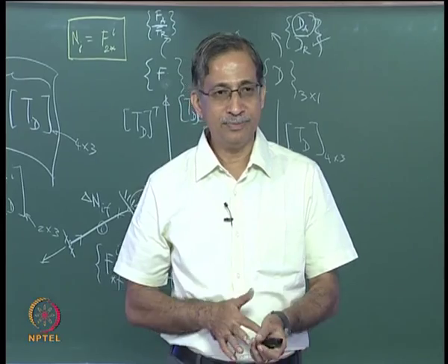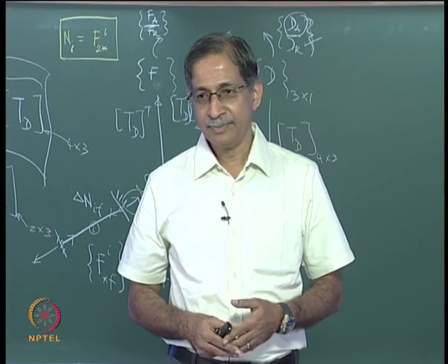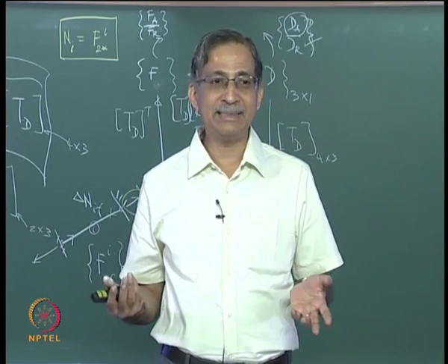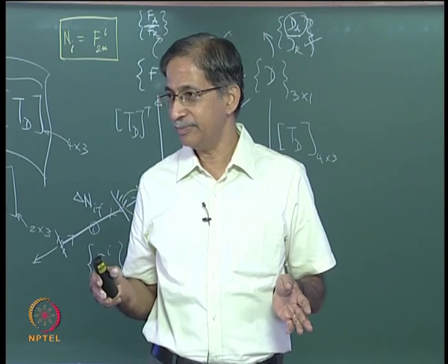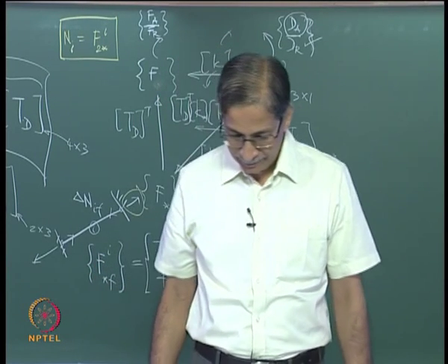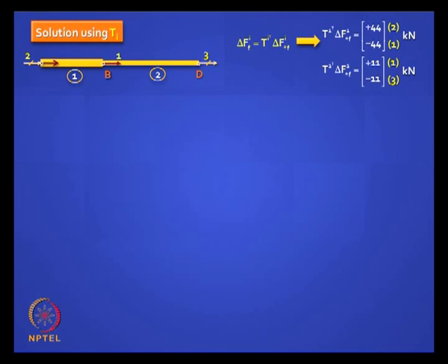Now what do we do? Now you release the active degree of freedom, right? So how do you do this transformation? Well, you have to move from element level to structure level, so you do this transformation, you have these matrices, but you put the linking coordinates.